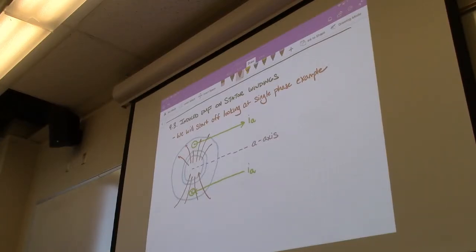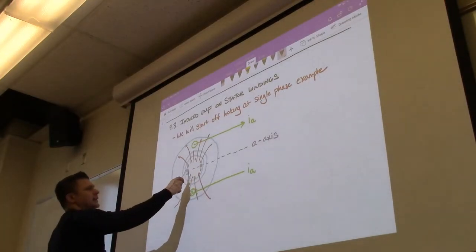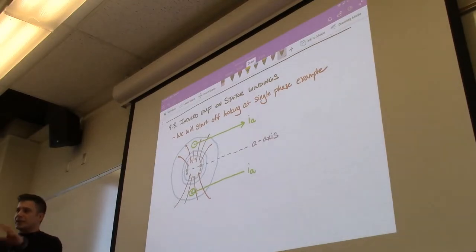And so if I were to draw the field windings, again, it uses that sinusoidal distribution, but really what we're concerned with is, like we're doing for the stator winding, we'll collapse all of these points down to here and here. So it uses that sinusoidal distribution, but equivalently, we can model it as these two single points.